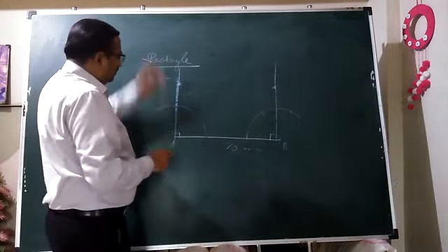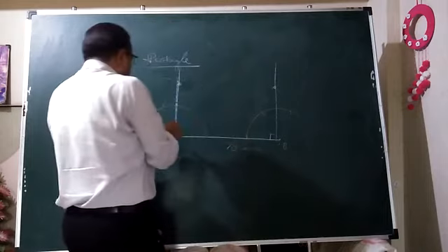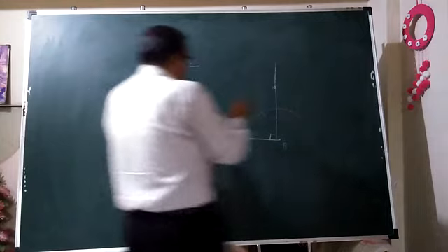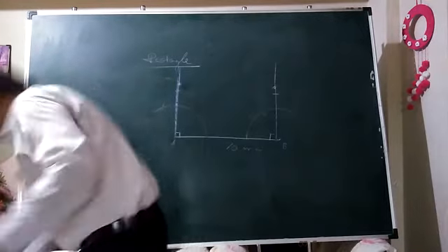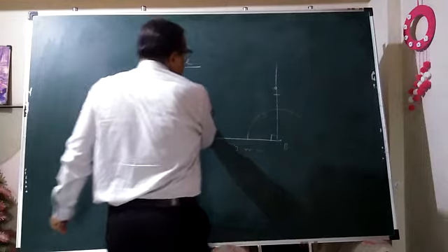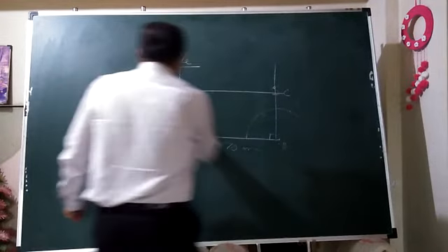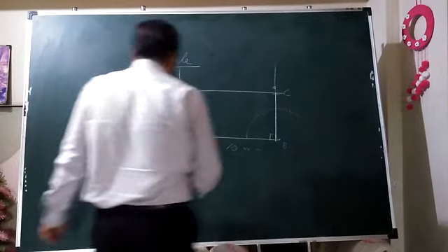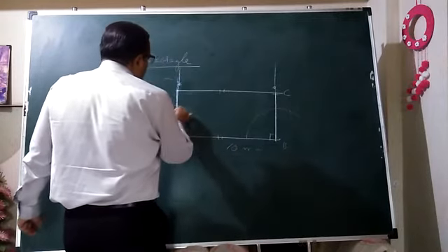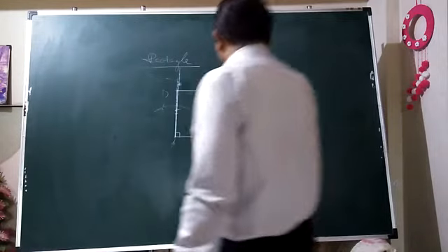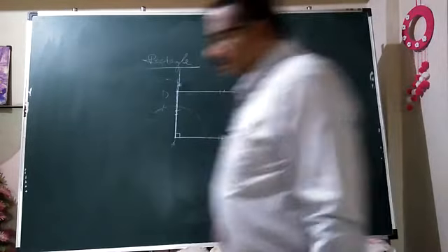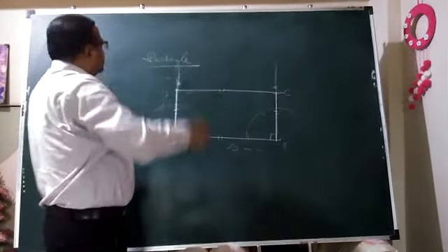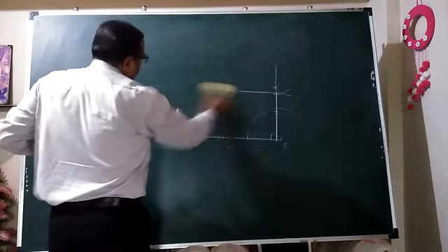its breadth above A and above B on these construction lines. How much is it? 40 mm. Yes. From A 40, from B also 40. I will mark, and simply you have to connect these points so that naturally A, B, C and D. This is the desired solution, rectangle ABCD. These two are lengths, these two are widths or breadths of the rectangle. Okay. This is required to be constructed in any manner, in this way or vertically, depending on the direction of the projection of planes.